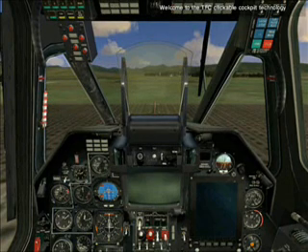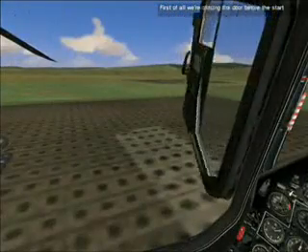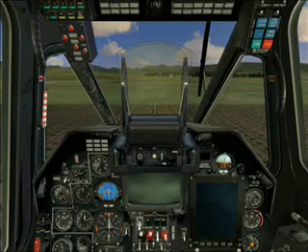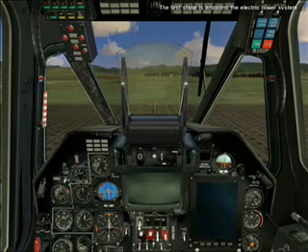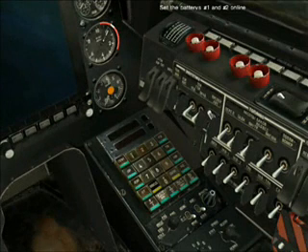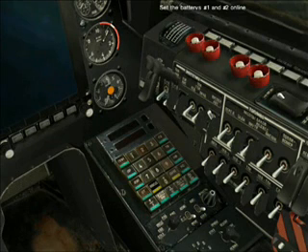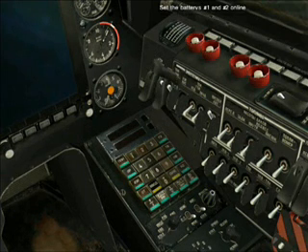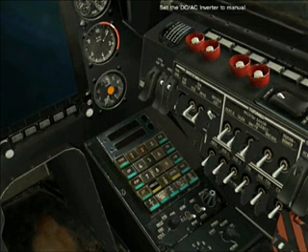The following is the startup procedure for a Ka-50 helicopter. Let's close the door before we start. The first stage is to engage the electric power system. Set the batteries 1 and 2 online. Set the DC-AC inverter to manual.